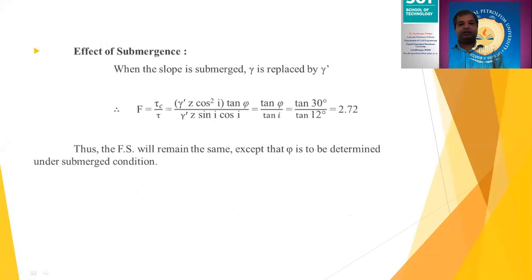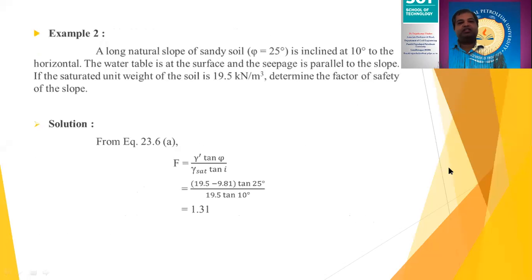Okay, so last time we have seen the slope stability for infinite slope, in which up till now we have considered two cases: the stability of infinite slope for cohesionless soil, and then the stability of infinite slope for cohesive soil, or you may say it is a c-phi soil.